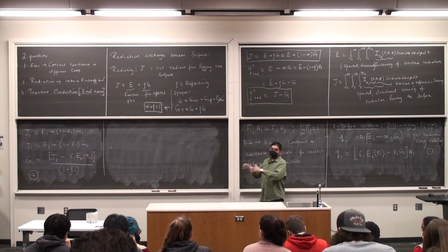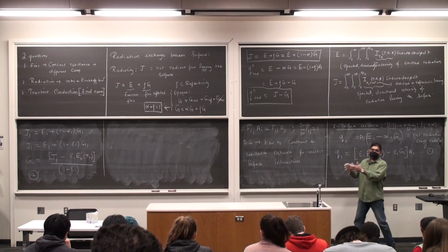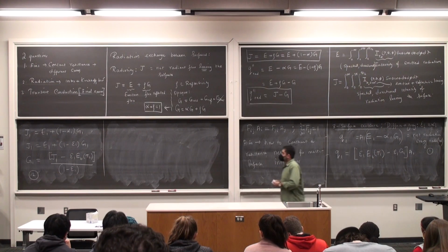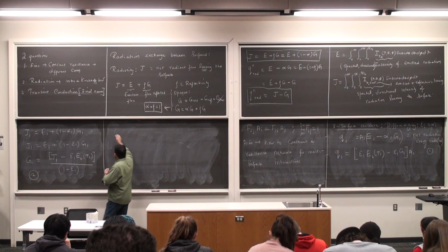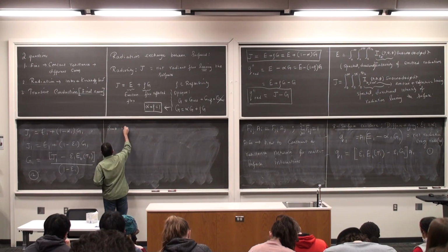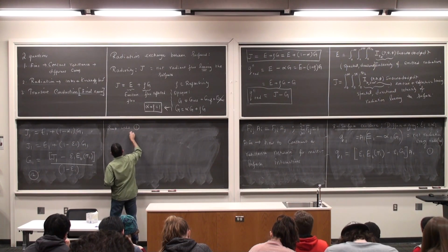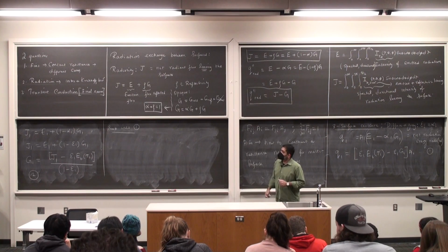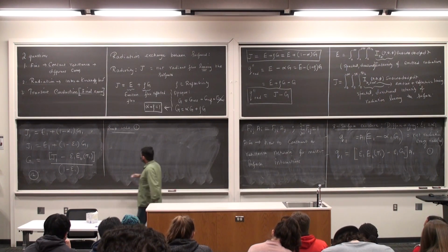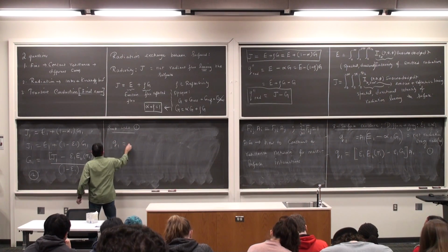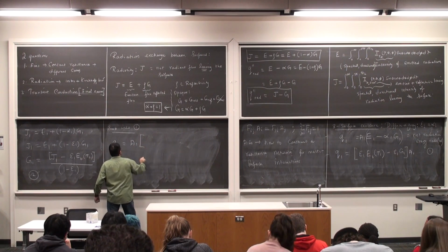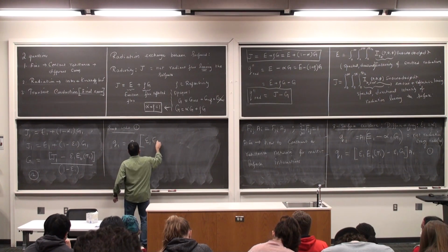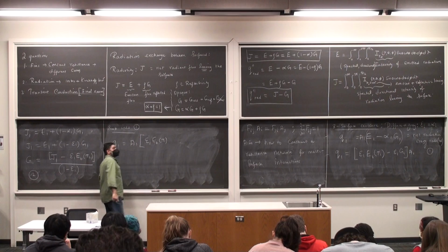I'm going to compare equation 1 and equation 2. Wherever I have a G1, I'm going to do the substitution. Okay, so substitute into equation 1. You see the fractions have not come into play. They will, don't worry. So Q1 is now A1 epsilon 1 EB at T1.